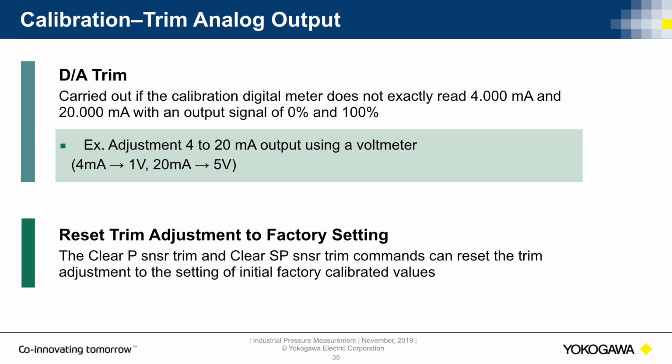A common one's like an absolute pressure transmitter. Again, like Jason talked about, you're referencing that at 0 absolute pressure is what it's being referenced. But if you zero that transmitter at atmospheric pressure, you've effectively turned it into a gauge, and you really need to clear that trim to get it back to an absolute measurement.